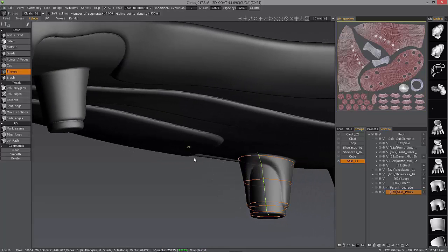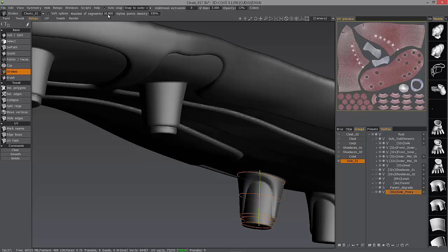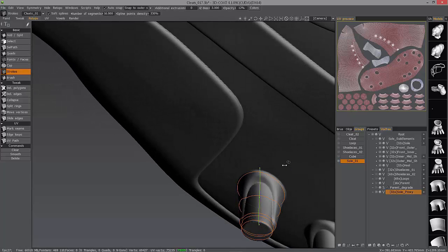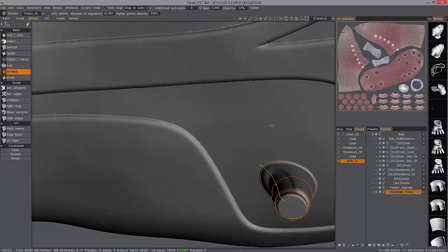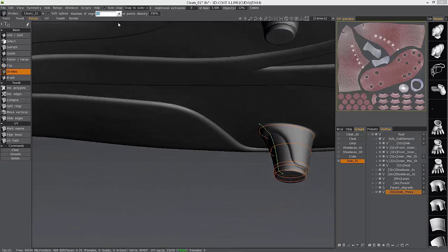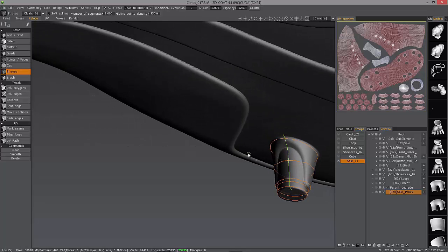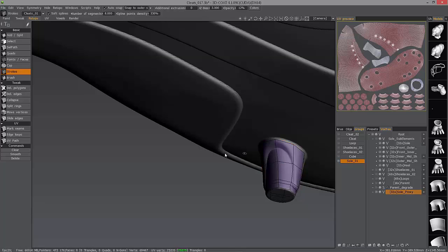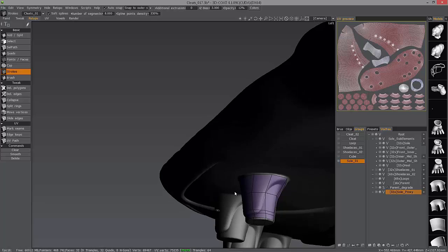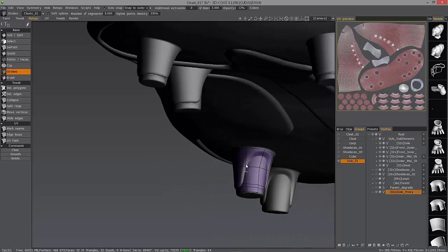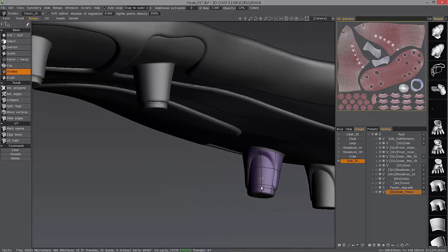So let me undo that. The more segments I have, the more connecting I have to do when trying to piece this all together. So I probably want to keep it as low as possible. So let's go with 8. Alright, so let's hit the Enter key, and so that's good. We want to keep that number pretty uniform with all of these, and I'll create my cross section right here at the same location so it's easier to connect these up later on.